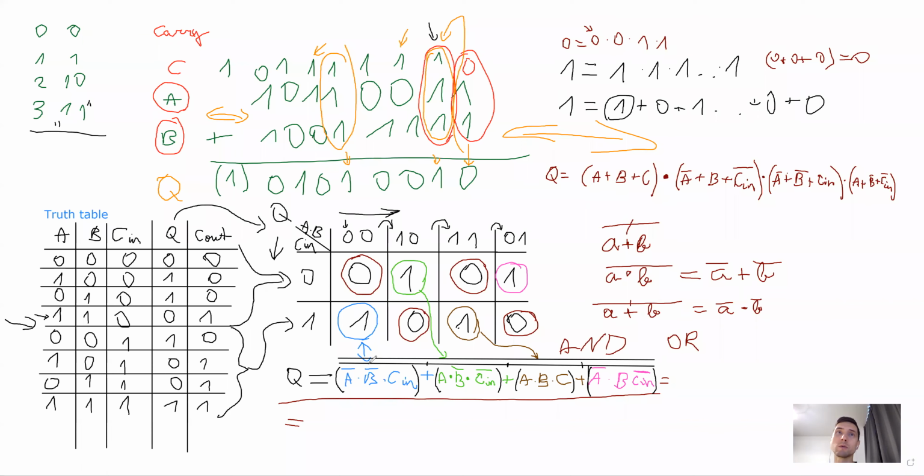And what we did is we have these multiplications in brackets, we do them first, and then we add them, and all of this we do double inversion, and then we break this bottom line above the places where we have pluses. It's completely legal. And what we get is we change the sign from plus to multiplication, and the inversion sign remains over each of these brackets. So I'll rewrite it like this.